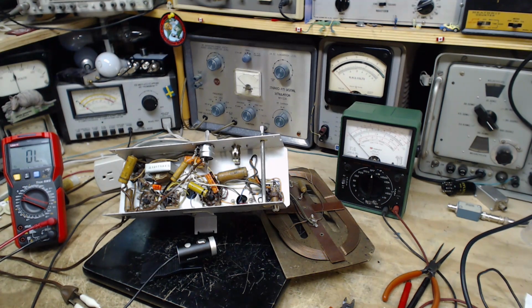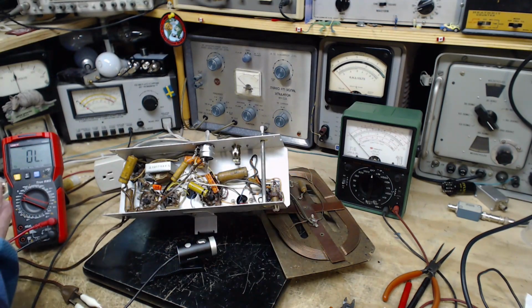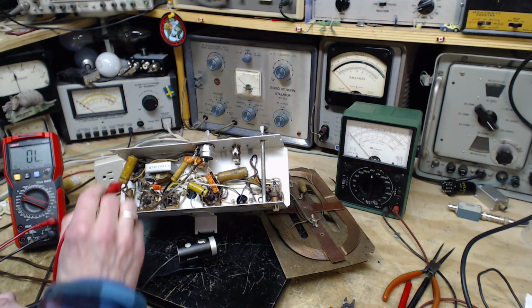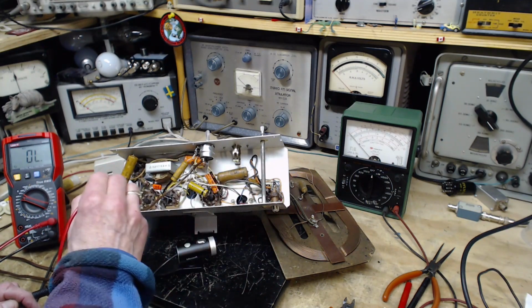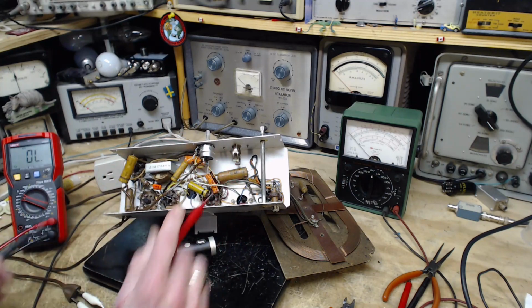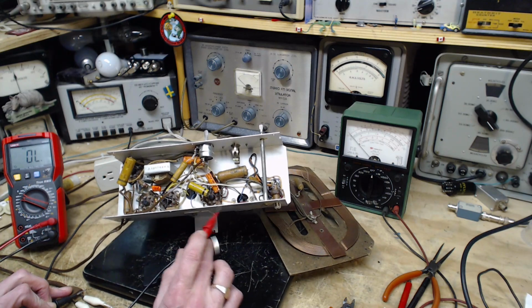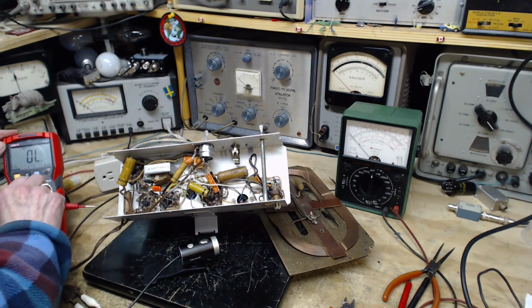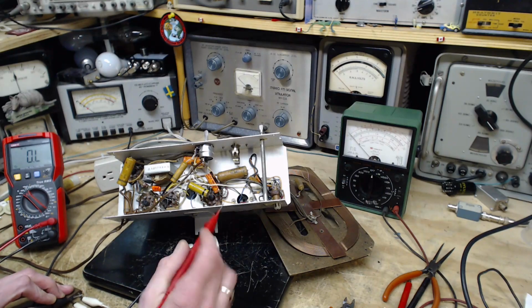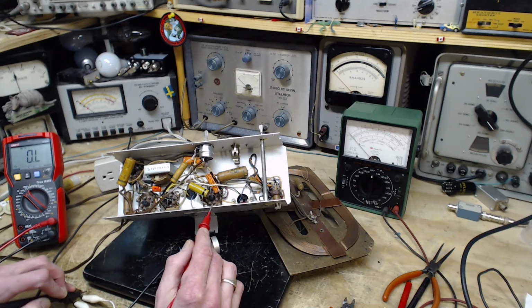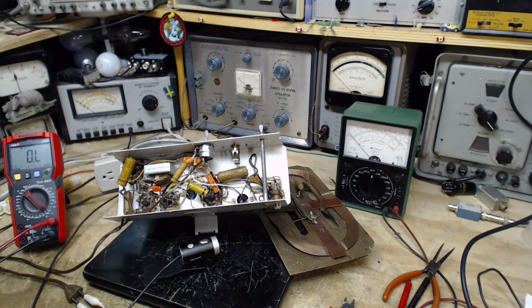So I want to read the resistance now between the chassis, which should be disconnected, and the power cord. Power cord representing everything inside here. So basically, is anything inside here somehow feeding current into the chassis still? Here we go. Okay, it's open. I'm going to put this right up at its maximum, 60 megohms. That's a huge resistance. So this suggests complete isolation now of the chassis from the radio inside.